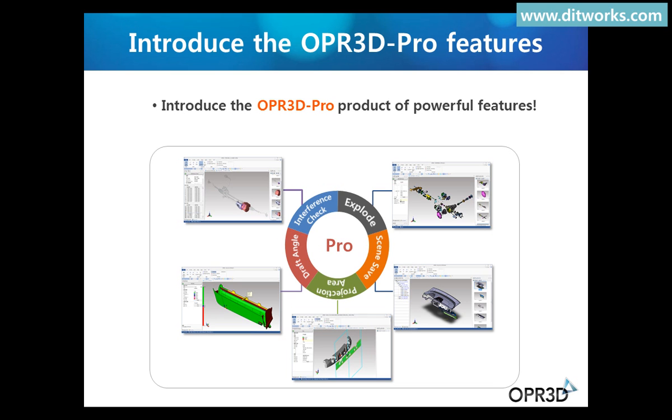The fitting bound box function measures the outer dimensions of a tilted model without changing the reference axis. The draft angle function measures draft angle conveniently and can display the angle by color, and the undercut function determines the angle and coordinates immediately by using the mouse. Finally, it provides a variety of functions, such as drawing and modifying in 2D.